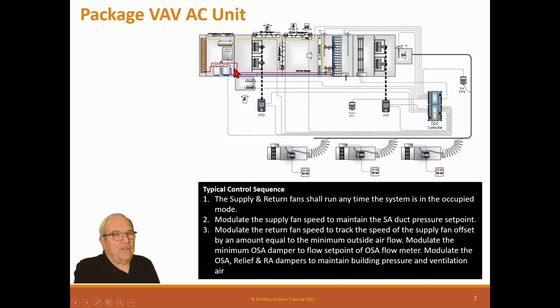On these, they don't have thermostat lugs because this is way too complicated. A thermostat cannot run the system. It must have a DDC control system to run it, and it might be internal like this one. Trane will do an internal one, but maybe not. Maybe you just need to have an outside one. But most of these will take a network control inlet.